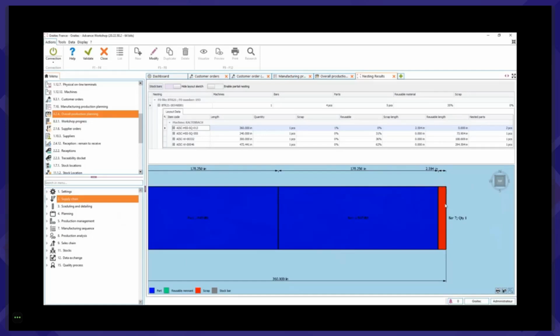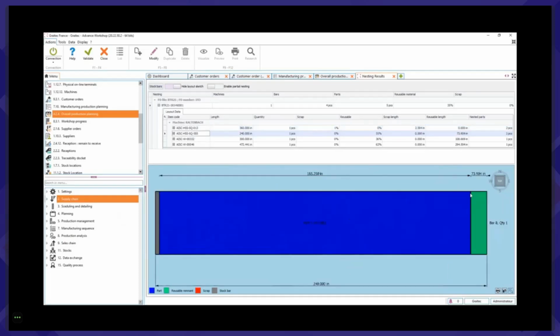And here you may notice that this portion is in red, so there's only 2.5 inches more or less of scrap of this material. But if something exceeds the predefined length to be thrown back into stock, so if there's a remnant that you would want to use on future projects, you could set predefined minimum values for bars. And here my settings are for 2 feet. So because here this length is exceeding 70 inches, so 73 inches, it's suggesting that this is an item that will need to be put into stock afterwards, or we want traceability on that remnant.